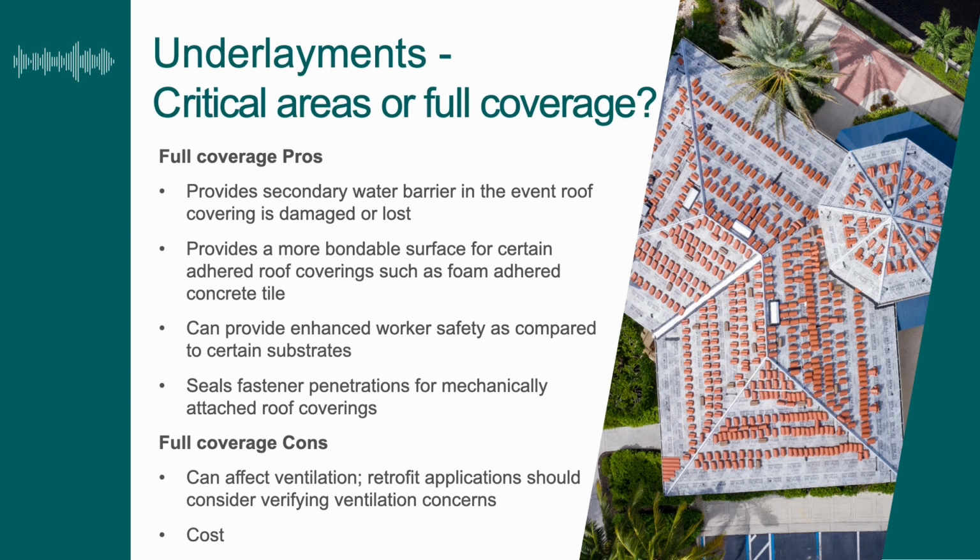Advantages are many here for going over the entire deck. We talked about providing a secondary water barrier and the advantages that can have in severe weather events. So you're really completely covered there with another layer of protection, in this case something that's dedicated specifically to waterproofing. It does provide a more bondable surface for certain adhered roof coverings.